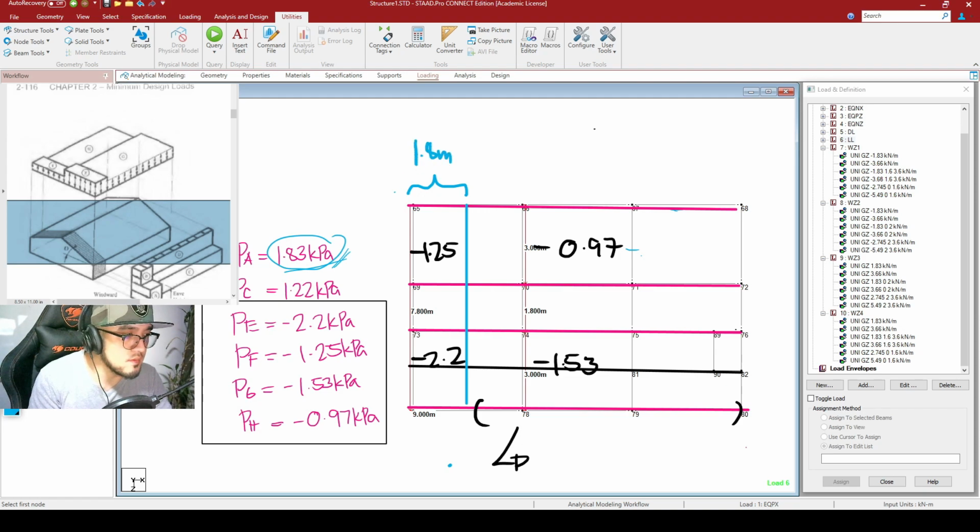And this once again is to be 2 alpha, or 1.8 meters. Okay, so solving for our line load, the tributary width of this particular beam right here is half of 3 meters. So this is 3 meters divided by 2, and that is equal to 1.5 meters. Same is true with this one right here, 1.5 meters. And what is half of 1.8? If this is 1.8, this is now 0.9 and 0.9. Then same is true with this, so this is 1.5 and 1.5 respectively.